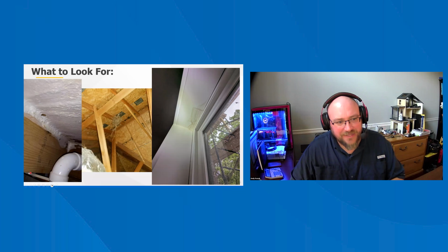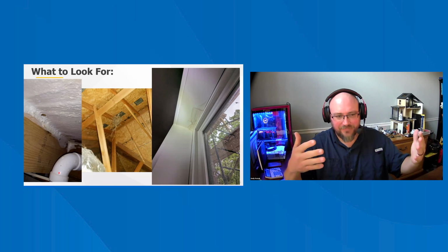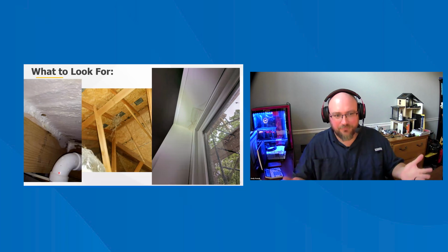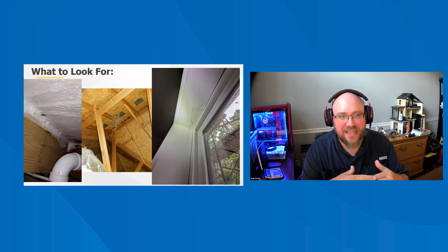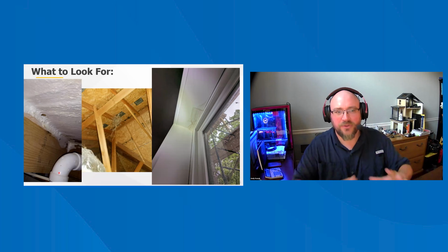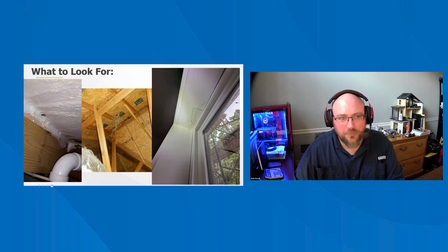Because the kraft face was installed over the bottom of the floor joist on both sides, the water was not allowed to drain into the crawl space. The kraft paper actually kept the moisture inside the fiberglass insulation, and it basically created its own little sauna in that floor bay. Then just a little bit of mold, I don't know what type of mold this was, I didn't test it at the time, but that little bit of mold colonized like crazy.